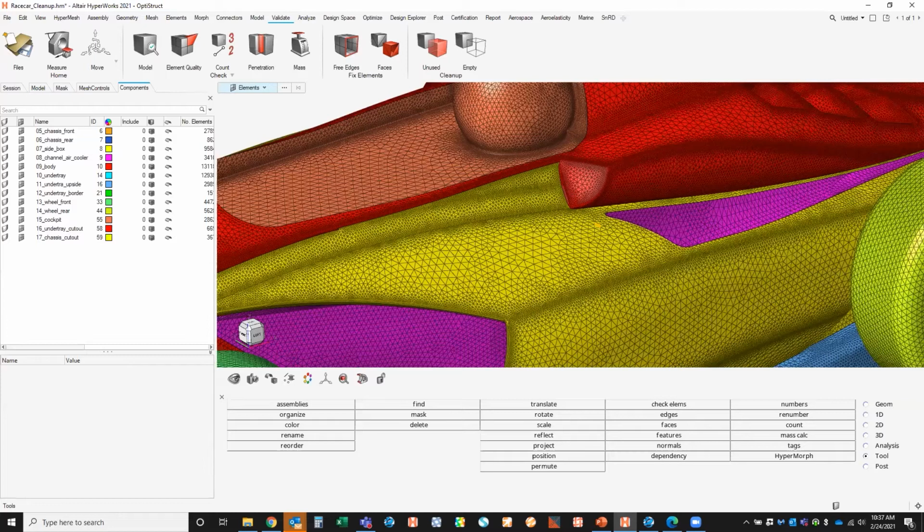But I just made a note that if they use AcuSolve, once they set up the model correctly in Hypermesh, they just go and run it within Hypermesh, so they can launch it from there, which will be a little easier to set up, unless they want to launch it on a HPC type computer. Right. Okay.